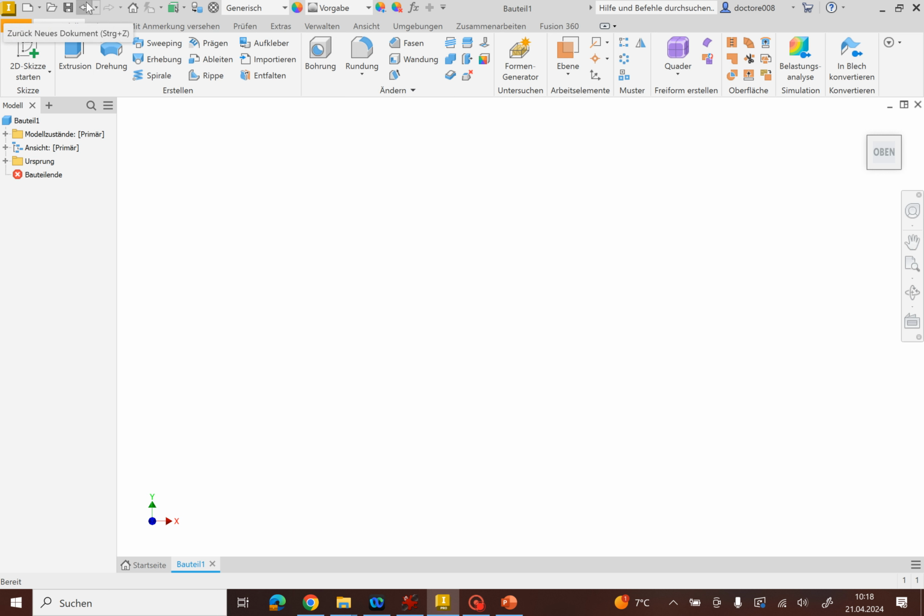We don't actually need it, because every mistake can be corrected here in our history tree. So we go directly to the steps. All the steps that we do are listed here, and then we go into the step and change or modify it. We don't use this go back button over here, and therefore we have this history tree on the left side.